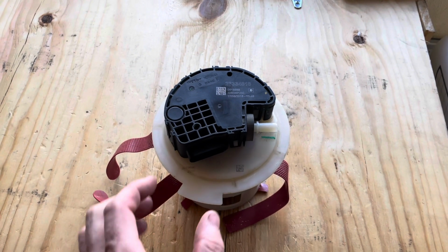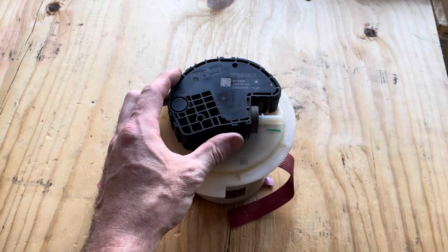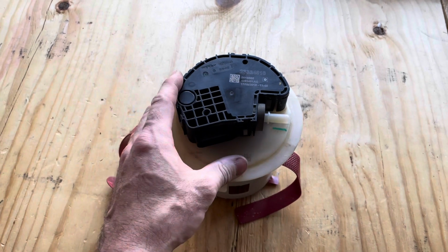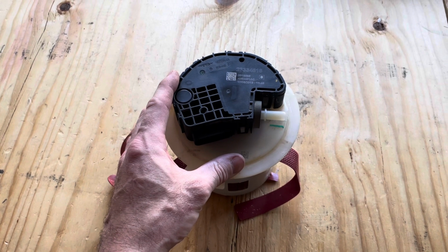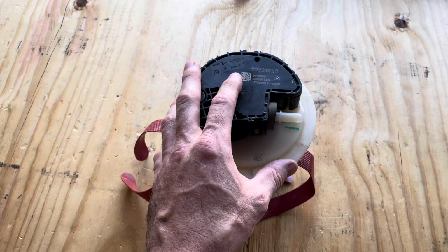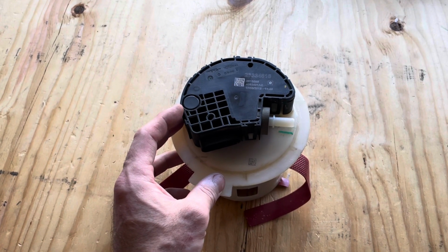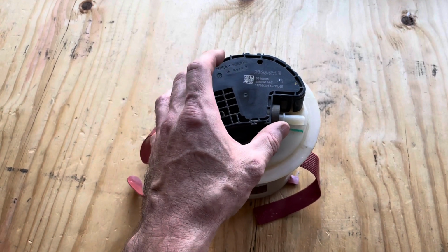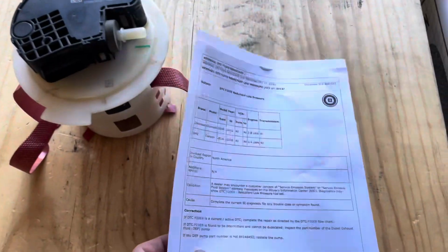So to summarize, we had a P20E8 code. The customer brought it back in. He was a little bit upset. He thought that the previous repair was going to be warranted. Turns out that was not true. The testing for P20E8 was pretty simple. It just said check for any leaks, check for a leaky exhaust fluid injector. You'll notice I did not even check the injector. I felt I didn't need to, and also I found an outdated old bulletin.